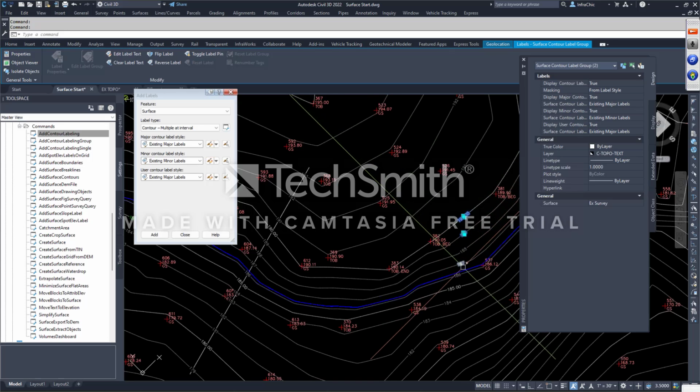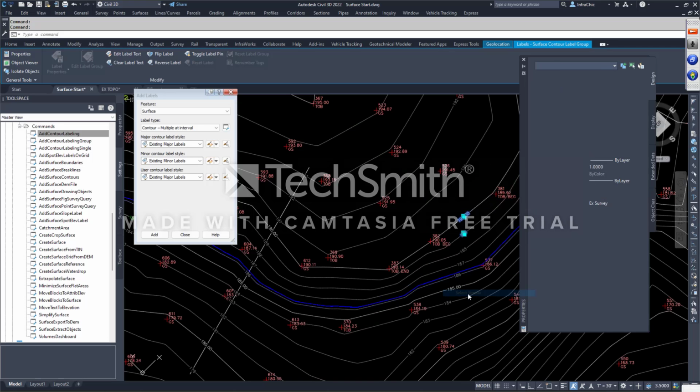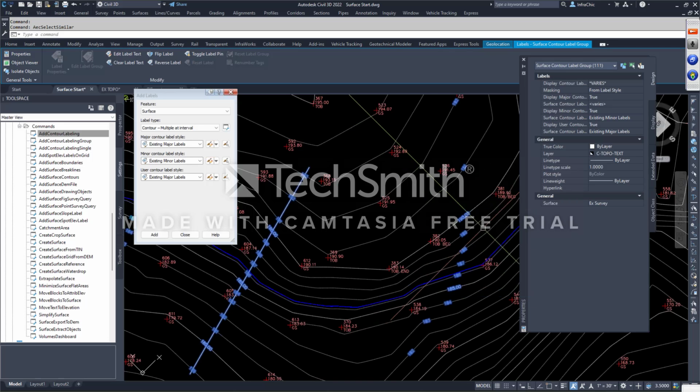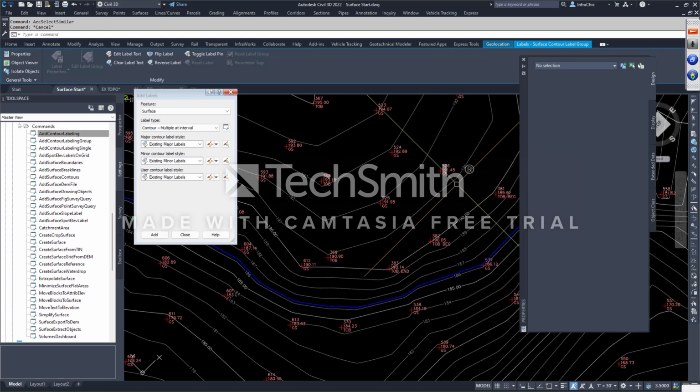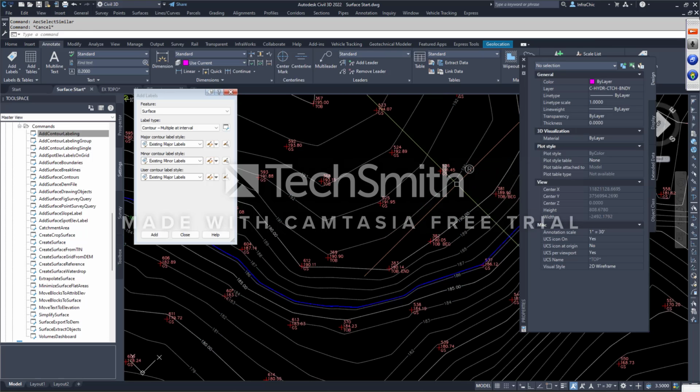So you can do an en masse change. Select 2 of them, right click, and do select similar. And it grabs all of them, all 111. And now it says, hey, it's on 2 different ways, so it varies. So I hit varies, and I go, I don't want to see any of them on. And I say false, and it does them en masse. Okay? So you can do that. Don't be afraid to do that and turn them off.